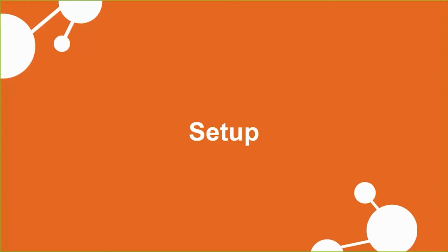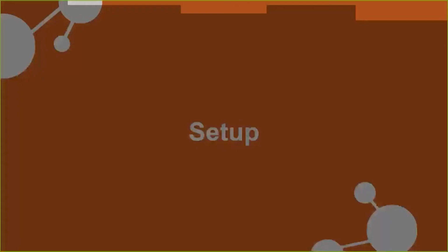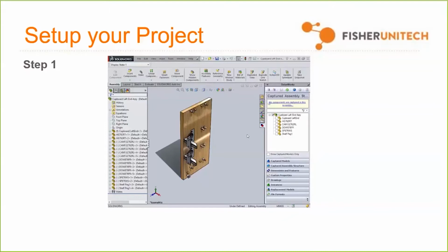Now, you bought DriveWorks or you have DriveWorks. How do you set the thing up? So what you can see here is DriveWorks in the SolidWorks environment, and you have DriveWorks Administrator living over in the task pane to the right. Now, the task pane is where you look to use DriveWorks whenever you're in SolidWorks. It doesn't matter which package of DriveWorks you have, and there are three. You have Express, Solo, and Professional.